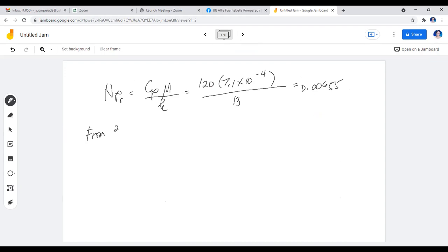We can directly substitute, so that hL is equal to 0.0625 times the Reynolds number times the Prandtl number, raised to 0.4, multiplied by the thermal conductivity, and everything divided by the inner diameter.